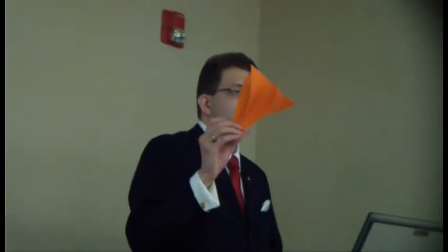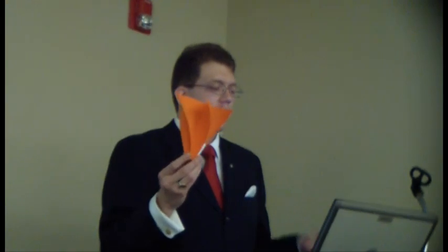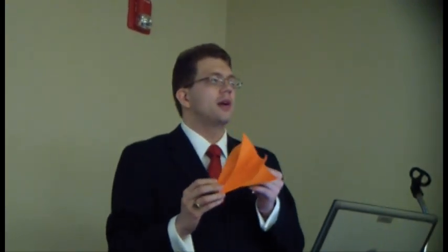Now, if you have overhanging details like you see in that image over there where you've got the hook over, you need to have support material below that, which is a different plastic that's made to be easy to remove. As the technology is getting better and better, the need for support material is being reduced.